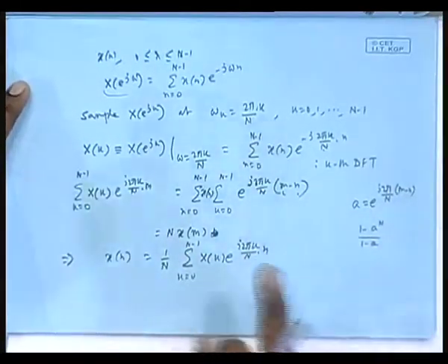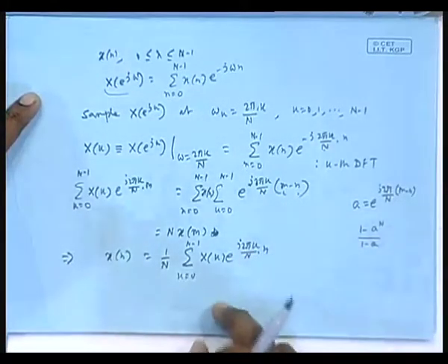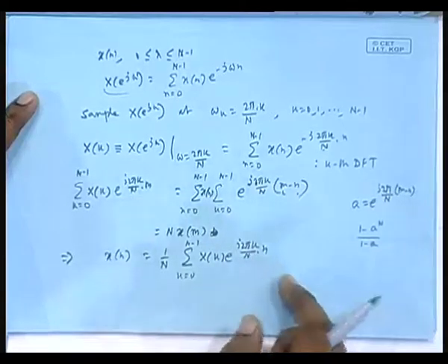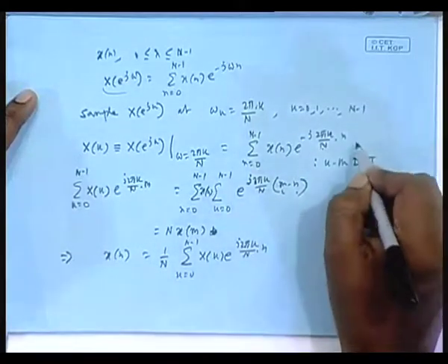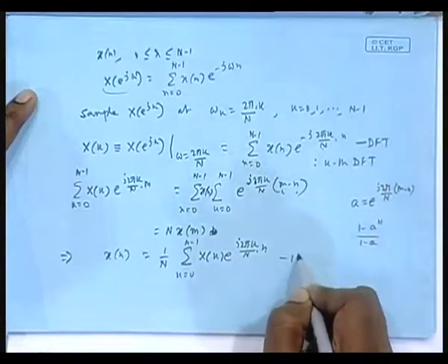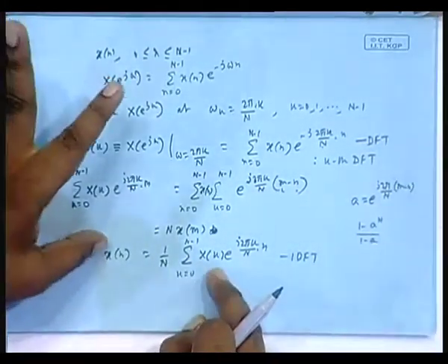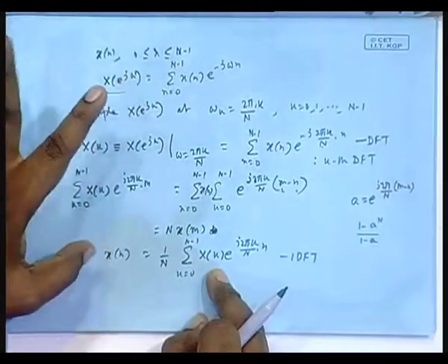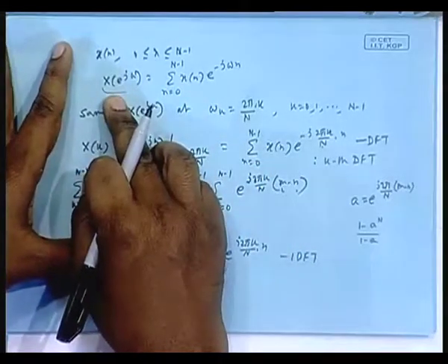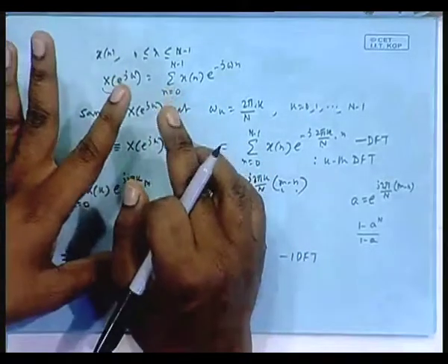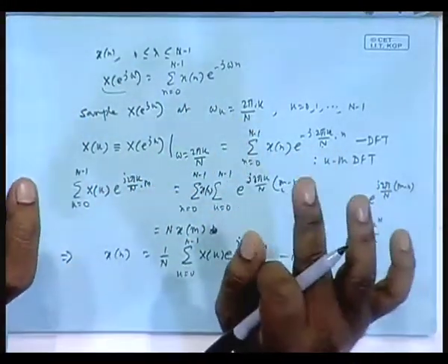When I teach all that in the context of orthogonal projection and all, for estimation problems, I will again take this example. That look, I did this that time. This is what happens. Okay, this is IDFT. This is your DFT. This is IDFT. Fine. So I proved my claim that from the samples of the DTFT I can get back x n, and from x n, putting back this x n here, I can get back capital X e to the power j omega. So the DTFT itself can be written by its own samples. DTFT samples are good enough to express the DTFT mathematically.